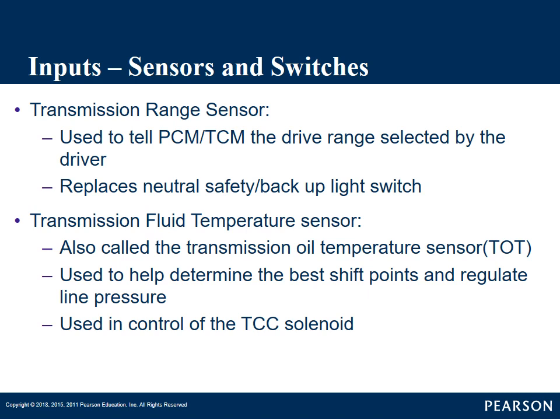Ford had a lot of trouble there for a while, that intermittent glitches in these sensors would cause the transmission to have trouble determining where to start at, how to shift the transmission, and you would get erratic shifting in these transmissions. So it is possible to have one of these out of range or have glitches in these that cause transmission shift problems.